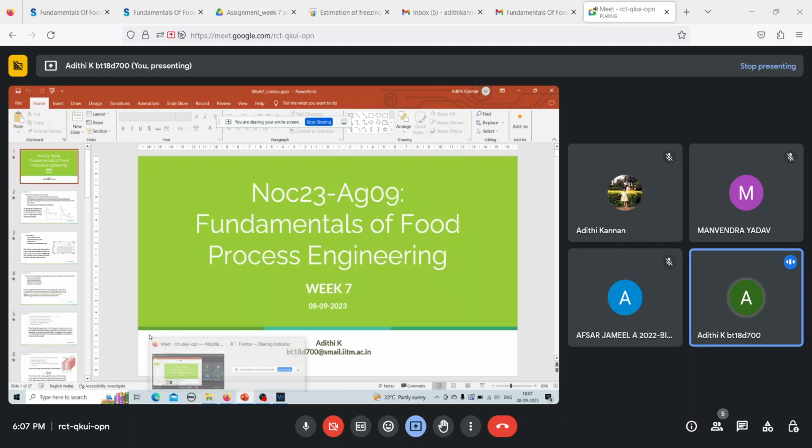So this was just latent heat for water. Now there will be latent heat of crystallization for the solute as well. Because of that, again you will see a slight increase in the temperature because the latent heat is being removed. Then again you have some other crystallization that is happening of the solute, and then finally after the entire product including the solute and everything has been crystallized and solidified, then further decrease in the temperature will lead to the post cooling stage where again the sensible heat is being removed. I hope this is clear. Is there any doubt in the freezing of the food material when compared to that of the pure water?